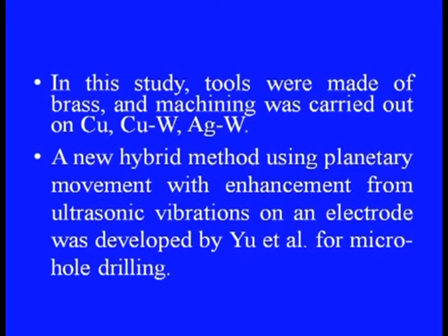A new hybrid method using planetary movement with enhancement from ultrasonic vibrations on an electrode was developed by Yu and his co-researchers for micro hole drilling. It was found that the use of these hybrid methods can give unevenly distributed gap for bubbles and gases to escape.